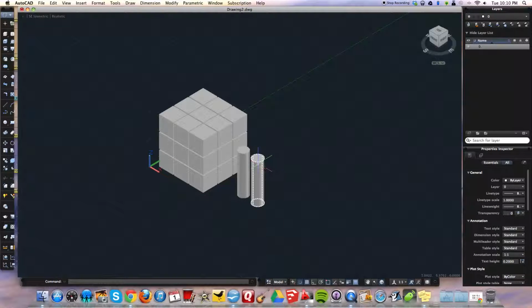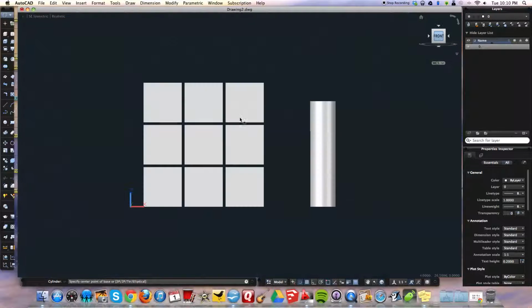So I would suggest using the tool that I just showed you, the object snap tool, the way that I showed you, where you can flip on the front face, and if you turn off the grid snap, and you turn on polar tracking and object snap, you should be able to hover over this midpoint, hover over this midpoint, and come to the middle.